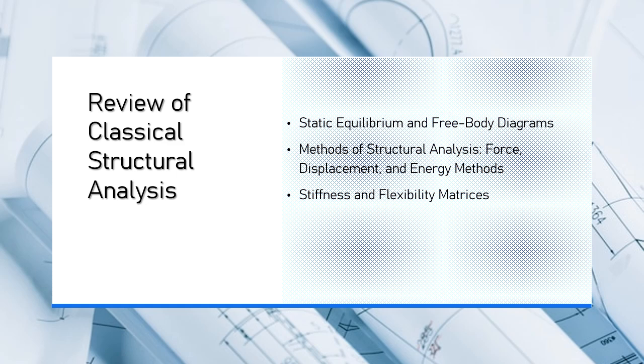The displacement methods are based on the following steps. 1. Choose displacement variables. For structures that are indeterminate, the unknown displacements, such as rotations or translations, are chosen as the primary unknowns. These displacements are the degrees of freedom in the structure, e.g., how much a point on the structure moves or rotates under loading.